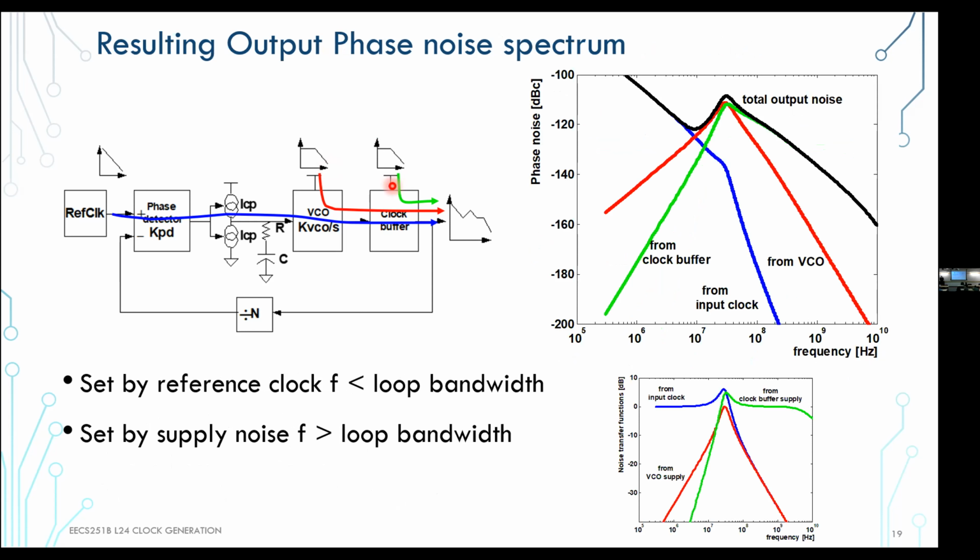And this is an example of doing exactly that. When we multiply these noise sources, you're now getting the phase noise plotted here. You see that within the loop bandwidth, we are basically tracking all the noise coming from the ref clock. Then the loop suppresses that, or rather the loop cannot track it beyond its own bandwidth, so it naturally gets suppressed.